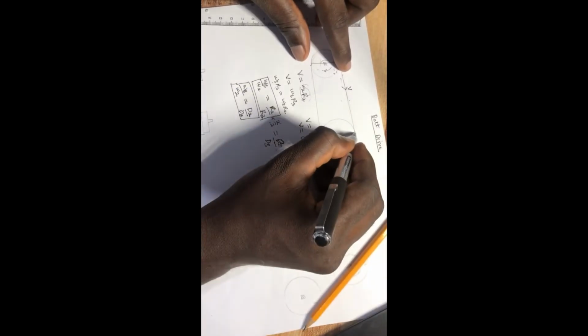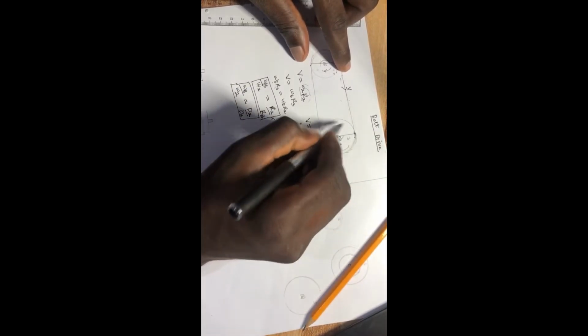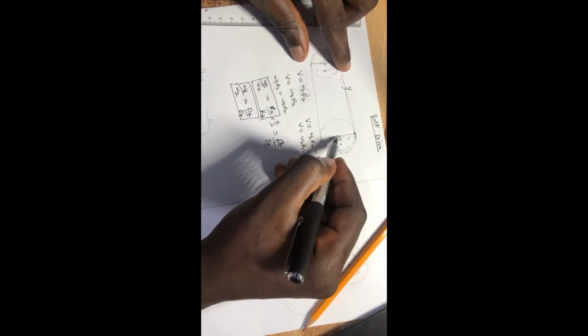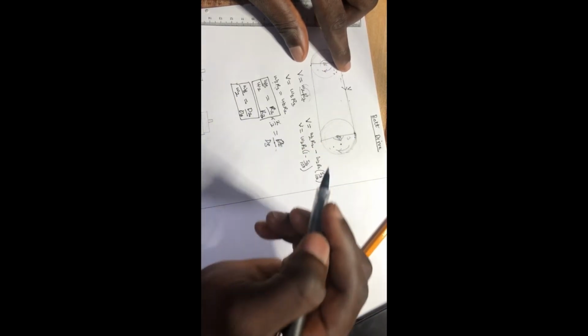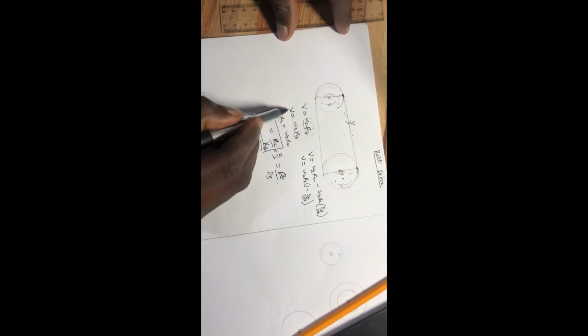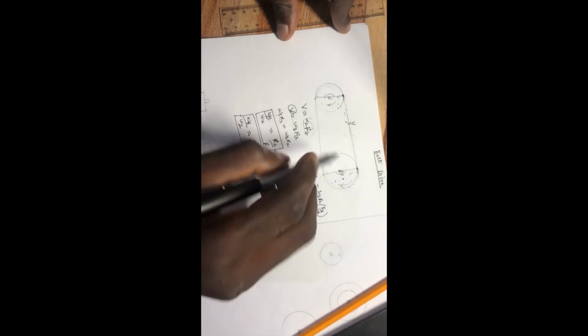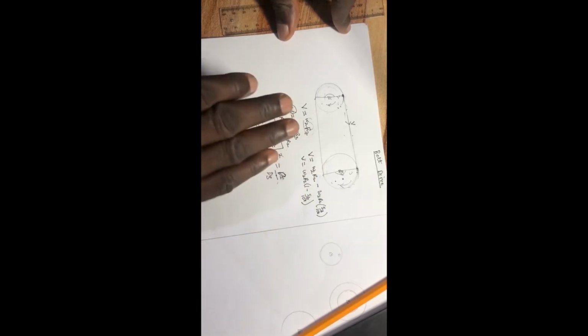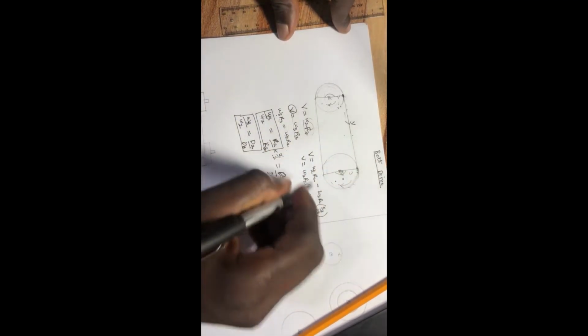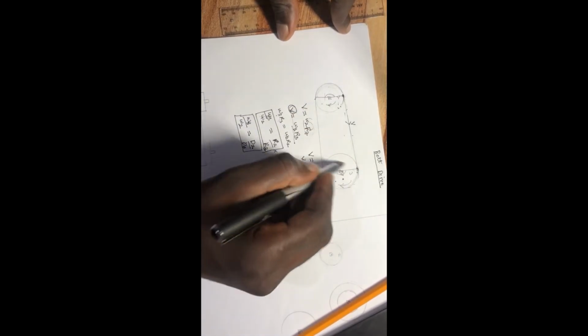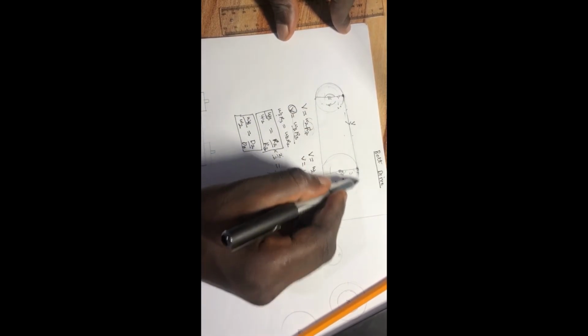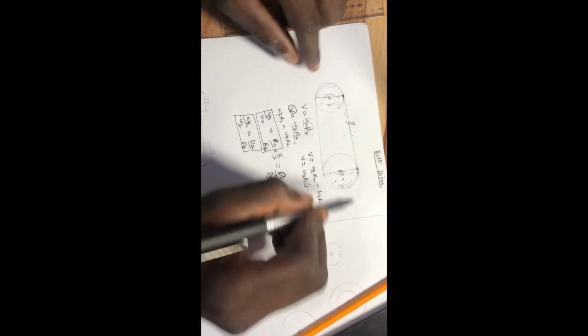So when this velocity reaches this point, it's supposed to turn the pulley around so that the pulley will also produce the same velocity, which is what we've stated here, right? That V should be equal to omega 3 R3. But because of slip, it can't transmit all of it to omega 3 R3. That means part of the velocity coming from the belt to turn this one around will be used in slipping, which causes that inefficiency.